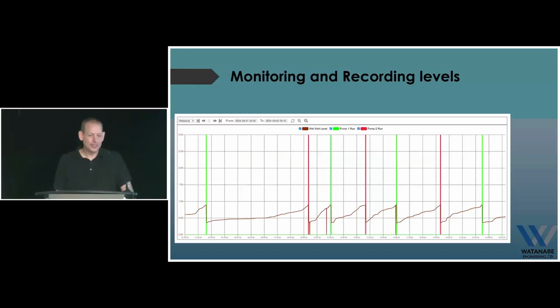So looking at these trends can really tell you a lot of information. Like I say, I was the SCADA guy for Chilliwack for 7 years. I was working with Chilliwack for 8, but did the SCADA for 7 years. And I pretty much looked at them every single morning. We had 56 lift stations, I think it was, so I got really good. They all had their own personalities in the end. I could tell which one wasn't working well based on its trends.